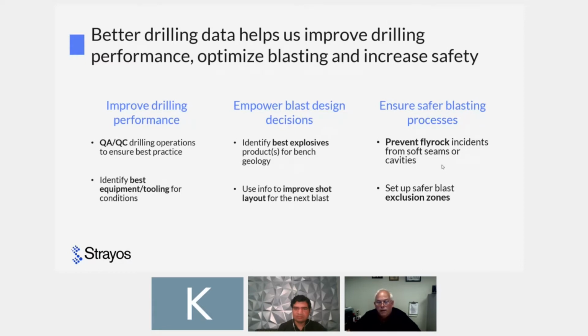So measure while drilling data helps prevent fly rock and also helps you set up safer blast zones. If the driller encountered something that was poor and on a paper drill log, they noted it. Also on this, it's noted all the time, and you don't have to rely on the driller paying attention. Next slide, please.